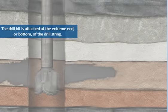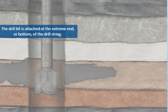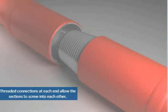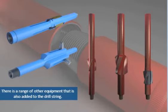The drill bit is attached at the extreme end or bottom of the drill string. The drill string is another name for the many short lengths, or joints, of drill pipe that are joined together as the hole gets deeper. Each section of drill pipe is typically 30 feet long and joined together by threaded connections at each end, which allow the sections to screw into each other. There is a range of other equipment that is also added to the drill string. We will look at these in later modules.